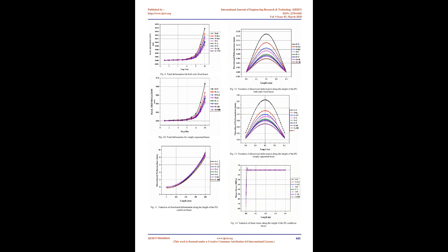The stress and strain under 100 kN force are tabulated in Table 2 and Table 3 respectively. And responses under other loads are shown in figures 5 to 7 for different boundary conditions. Both the stress and strain are maximum for n equals 0.1 for all boundary conditions except shear stress for the both ends fixed beam. For the both ends fixed beam, shear stress is maximum for metal constituents only. There is a dissimilarity in this stress and strain section compared to the previous deformation section.